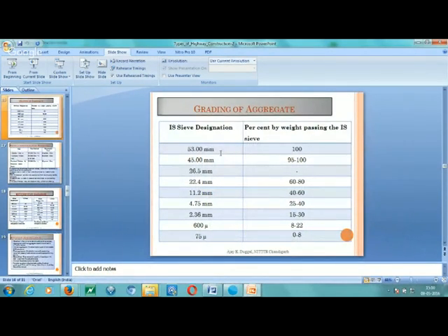यानी अगर मैं क्रशर पे जाता हूँ तो उसको कहूँ भाई मुझे वेट मिक्स मटेरियल दे दीजिए, तो कहेगा साहब मेरे पास तो 1 इंची है, 1.25 इंची है, स्टोन डस्ट है, जो चाहिए वो ले लो. So as an engineer आप वो सारे मटेरियल का सैंपल लेके उसकी सीव एनालिसिस करके, then you will find the ratio in which that has to be mixed so that you get the desired grading. ये grading जो है फिर हमें स्पेसिफाई करना होता है. और वेट मिक्स प्लांट, जैसे आपने हॉट मिक्स प्लांट सुना है, ऐसे ही वेट मिक्स प्लांट होता है.